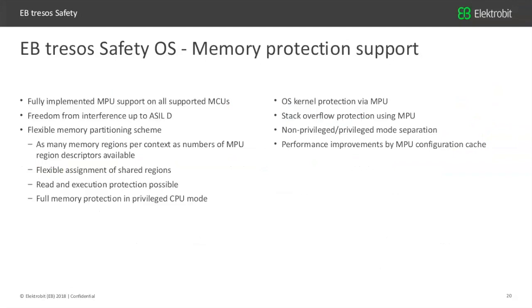On the memory protection support, I mentioned it before, the OS is actually taking the full control over the MPU and is doing the switching of regions automatically during the execution, and it is using all of what the hardware is offering to provide that service to the user and the application in that case.